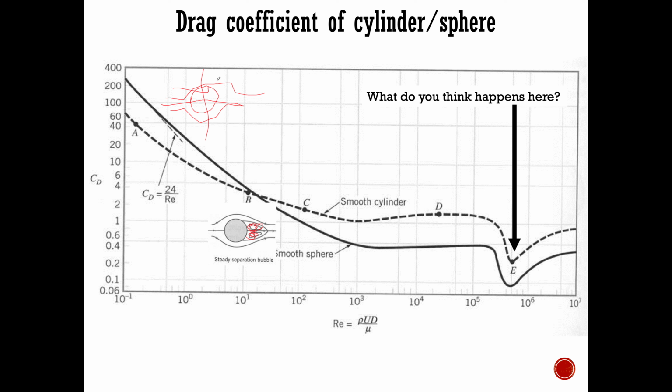Imagine you drop a cylinder in honey, right? You really have to push on it for the cylinder to go through the honey, or any highly viscous fluid. Otherwise it'll just sit there. That shows you that even though flow going around a cylinder or an object may look symmetric, the viscous forces still play a role, and the drag coefficient is a lot higher, right?